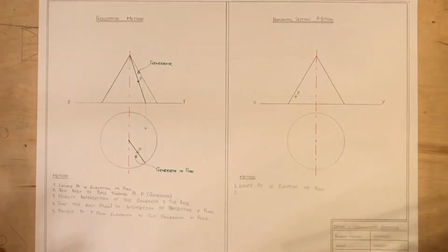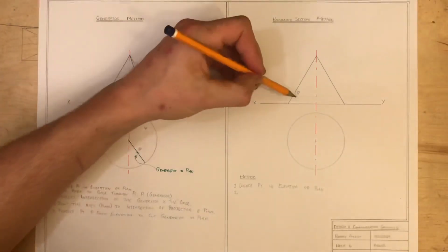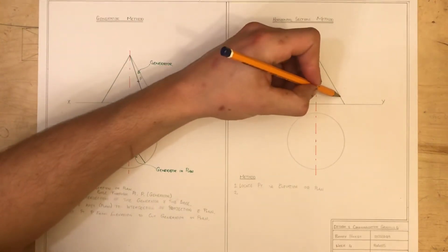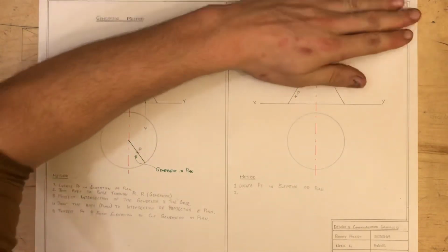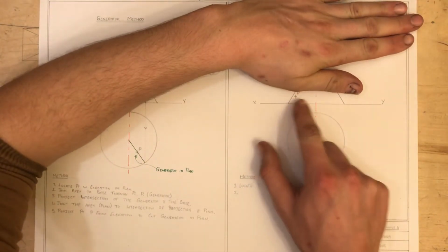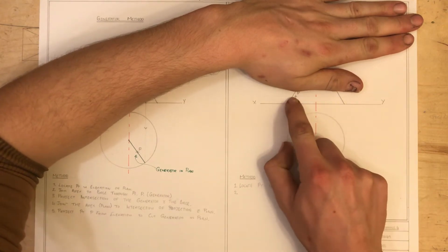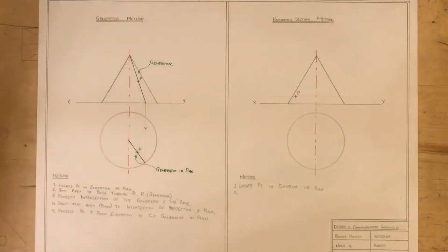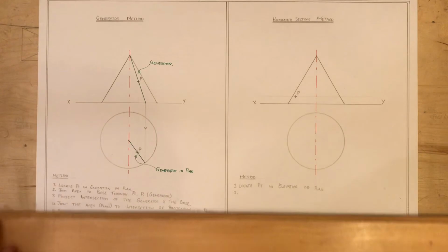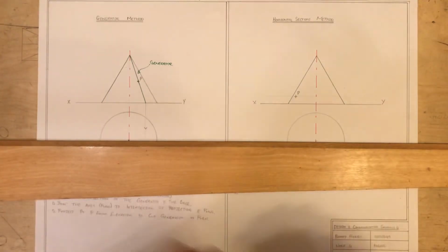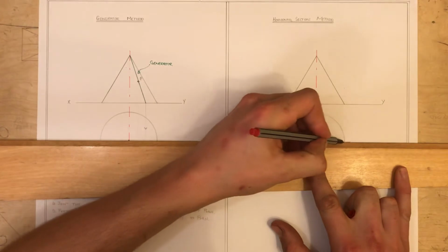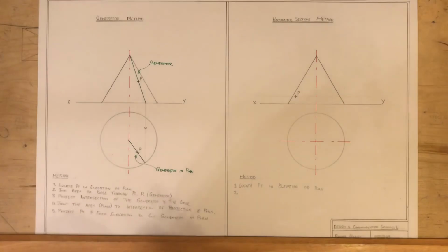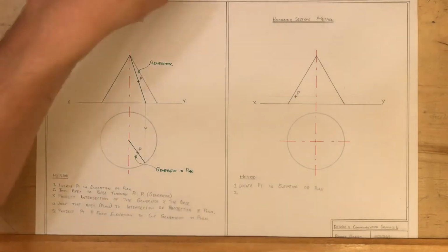So now I can see that for the horizontal section that this point goes through, if we cut off the top of this, our circle would have a diameter from the two intersections of the cutting plane with the cone. So I'm going to draw my center line in plan, and I'm going to project down these points.